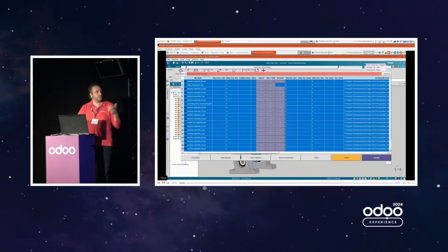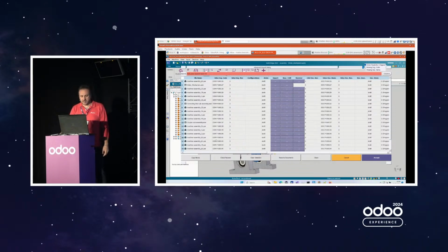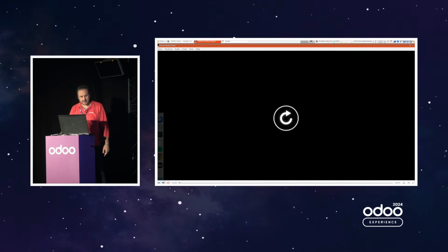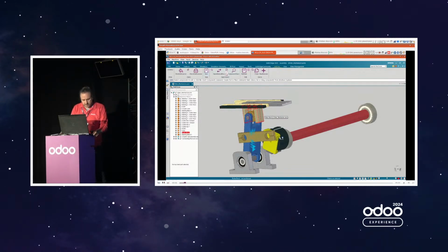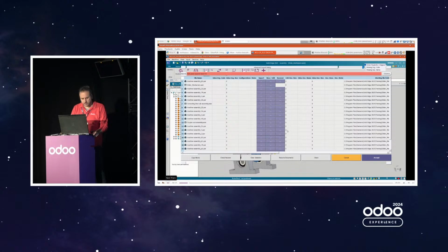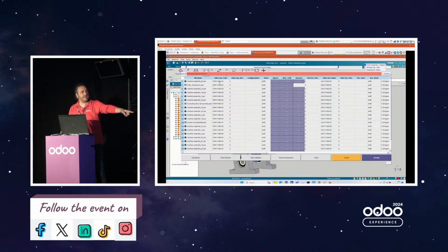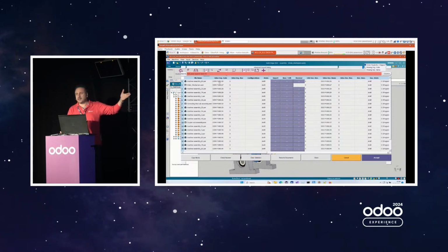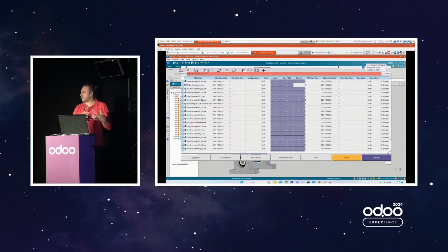Now what you will do is use this functionality, the copy name. This can also query Odoo and automatically assign the part number, as you can see. Sorry for this. Let's see. Go back. Okay, so now the Odoo code column will be filled with all the part numbers. The part number is assigned automatically, so it means that we can use Odoo as a repository for our part numbers.